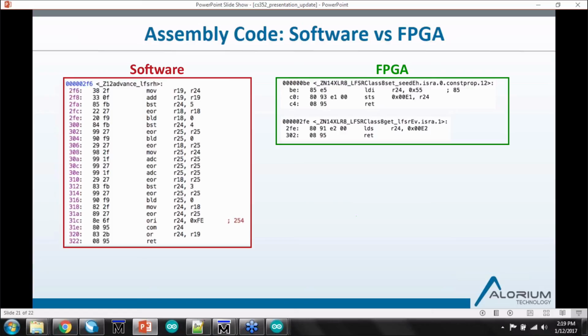The 8-bit LFSR is not a very ambitious program, but if you imagine, the more complicated the software is that you're trying to replace, turning that software into FPGA code, the returns on it are much greater. And certainly, as you said, when you get into some real complex software code, it is not necessarily trivial to unroll that into hardware.